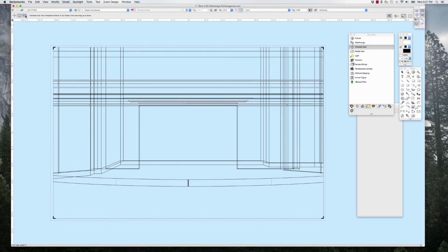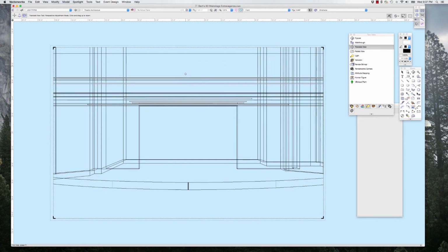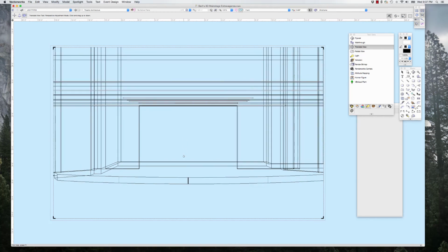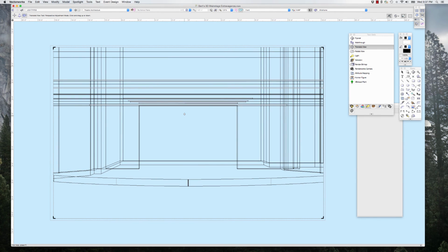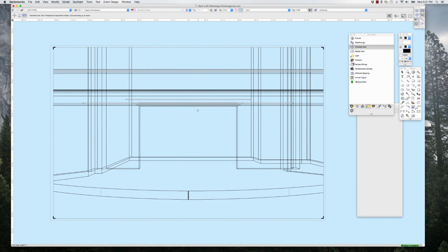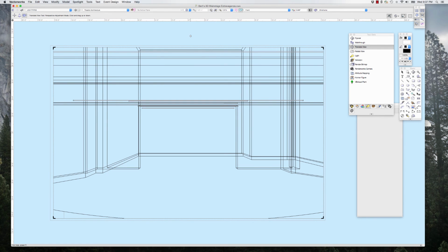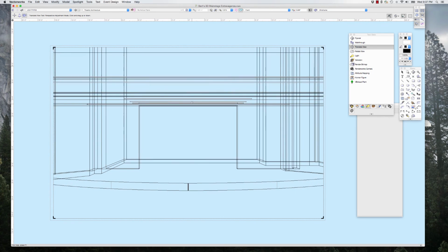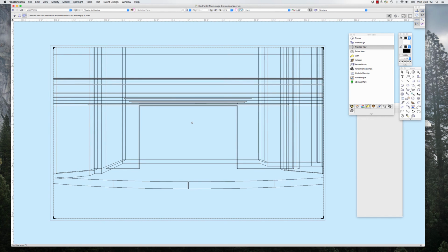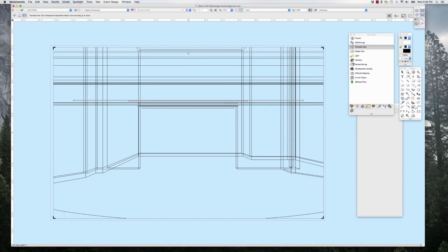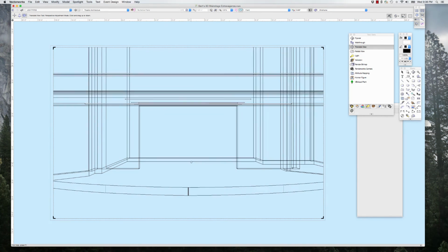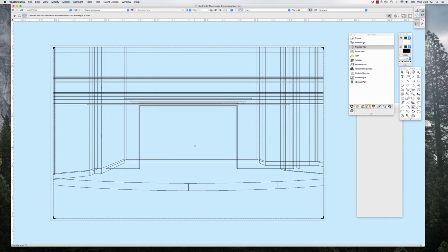The other tool here is the perspective adjustment mode, and this actually changes the perspective itself, making it narrower or wider. If you remember, I said when we originally started off in narrow, if you start off with a normal or a wide perspective, it really distorts the theater and gives you a false impression of what it looks like. Usually you want a shallower perspective when you're doing a drawing of a theater, or a rendering of a theater model. So I want something that looks more like this than like this. This isn't a realistic look at what the theater looks like. This looks more like it would if I were sitting in the audience, which is usually what I'm trying to do.